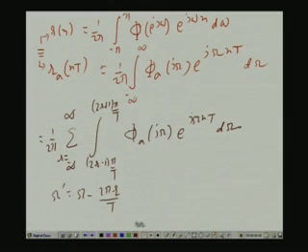Actually, what I am doing is always done in DSP, while proving the Nyquist theorem. So, there is nothing new, but still I am doing it. So, in that case, what will be the integration limits? When omega becomes 2 pi r by t plus pi by t, omega prime goes to plus pi by t, and minus pi by t for the lower case. Okay. And d omega prime is the same. Okay. So, I make these changes here.